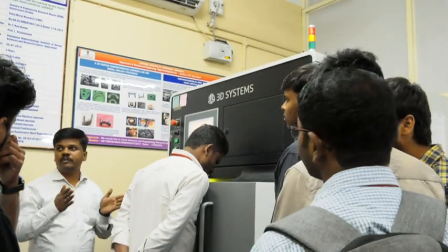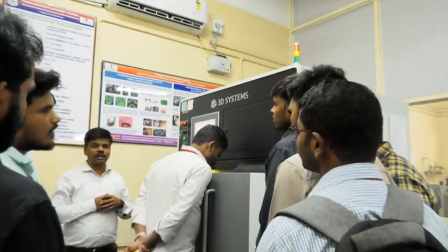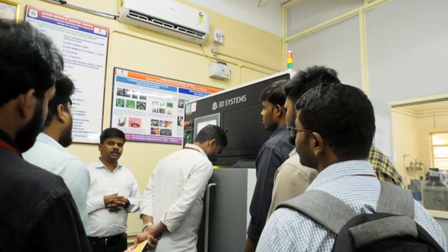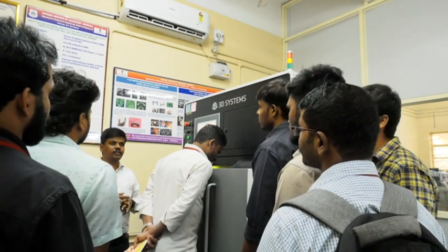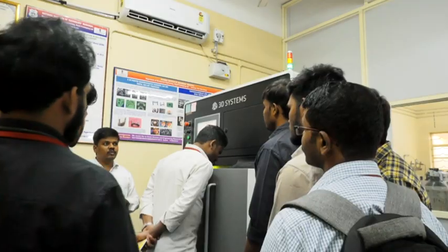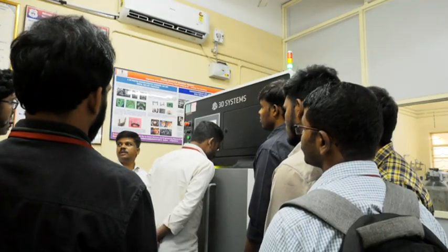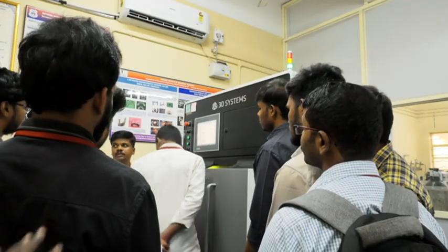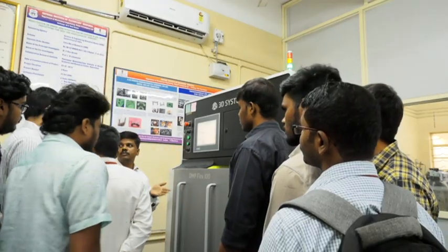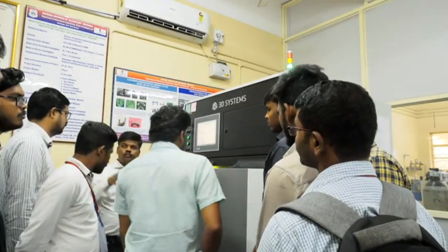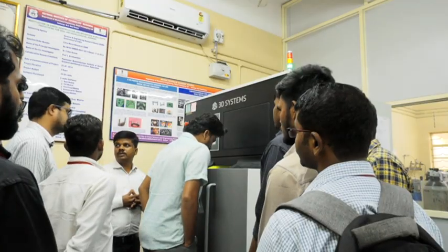The tension test specimen is 50 mm in gauge length with a thickness of 3 mm. We have defined that based on the ASTM standard, and based on that we can print and test. Whatever printing is taking place now is in the horizontal orientation. We are qualifying the method only in that direction. For vertical, again we need that much more powder.